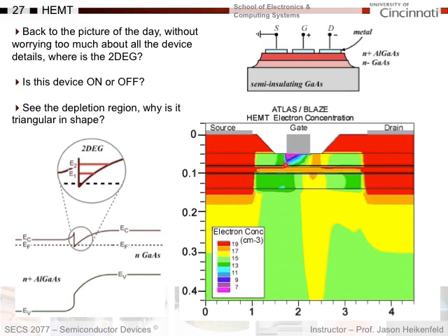But furthermore, whenever you see this triangular shape, you know you've got a voltage applied. And that's telling me that I'm getting extra reverse bias based on the gate to source voltage, and that the gate to drain voltage is somehow reducing the reverse bias in the depletion. So I'm getting basically that same sort of pinch-off type effect you saw for a JFET, where the channel has this sort of shape to it.